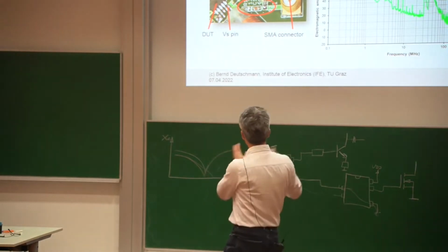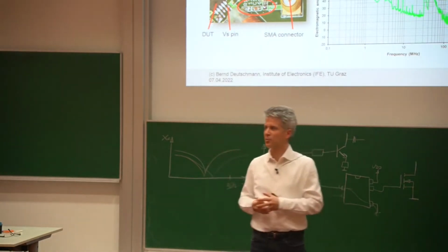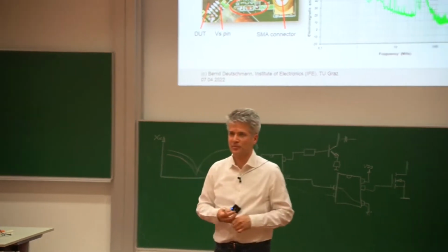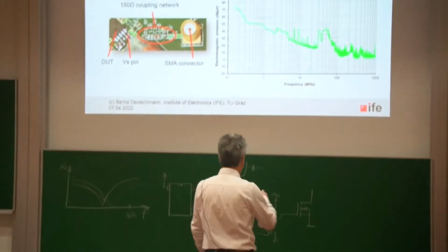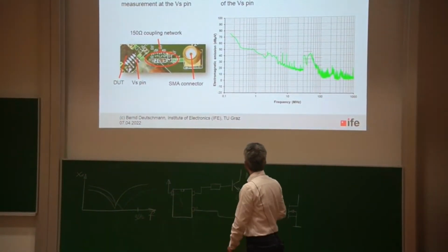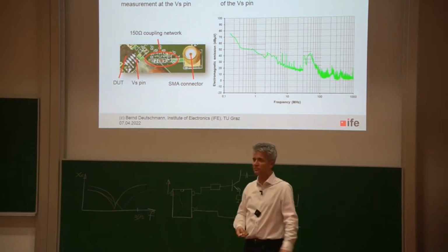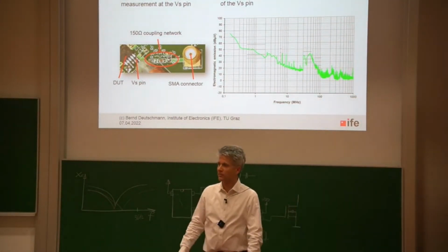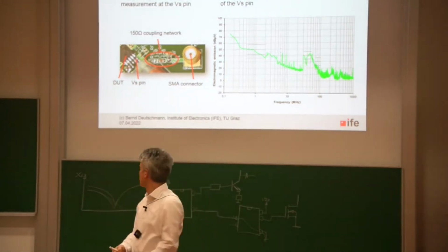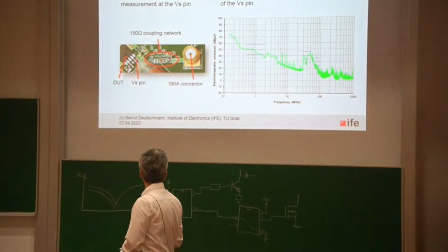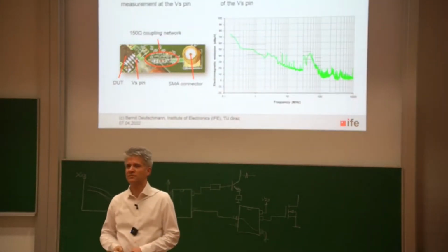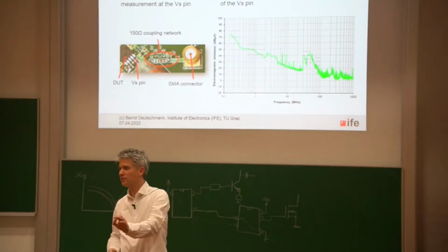Okay, then step by step, let's go to the most important things that we can extract out of this plot. So first, let's focus on why we have this rise in the electromagnetic emission, which is very sharp. Can the electromagnetic emission of an IC just jump over, whatever it is, 10, 15 dB microvolt? Not if you're measuring in the right way.